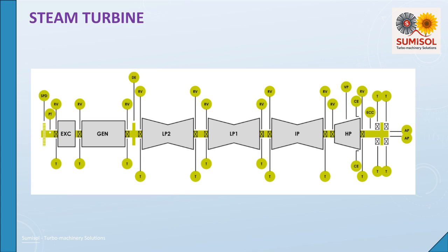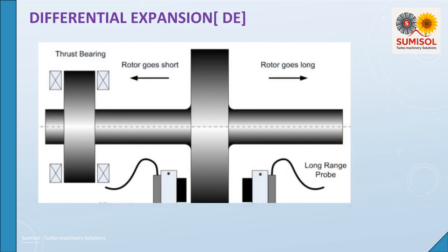The rotor of a machine is physically held in place by the thrust bearing, but depending on where the fixed or pinpoint is located on the machine, the thrust bearing can also slide as the machine expands. In any case, as the machine heats up or cools down, it is vital that the rotor and the casing grow at the same rate so as to avoid rotor-to-stator contact, which will invariably destroy the machine.